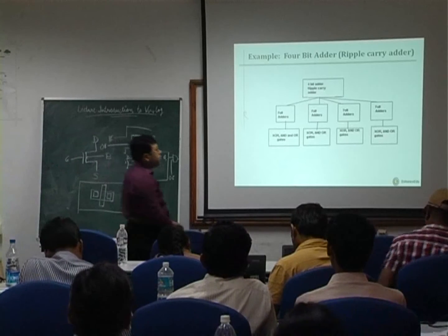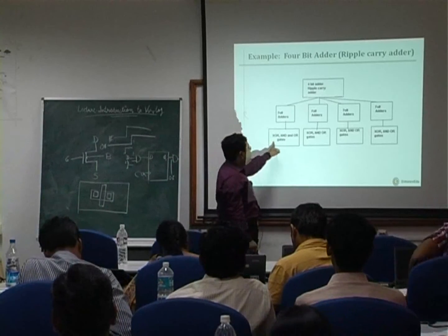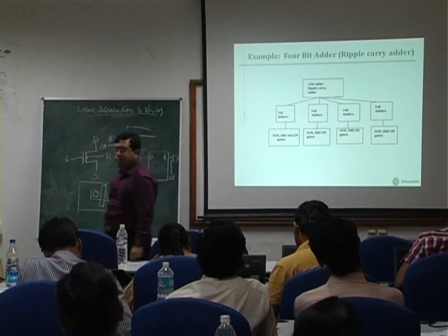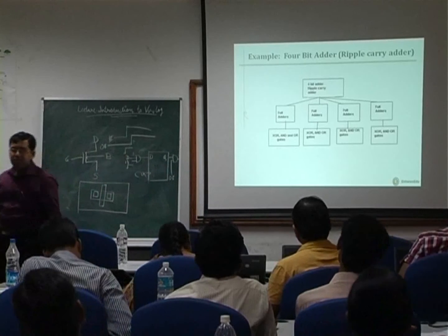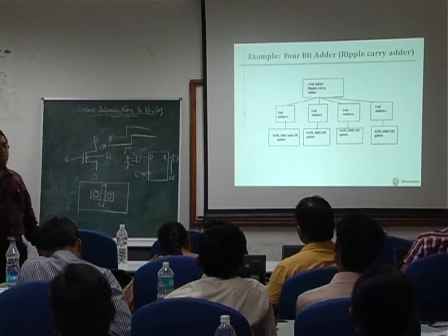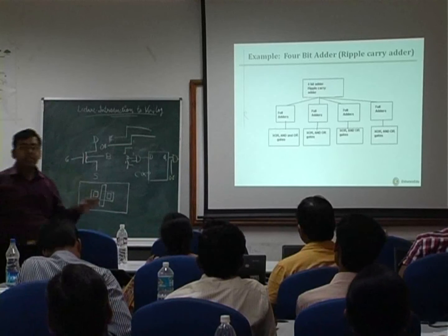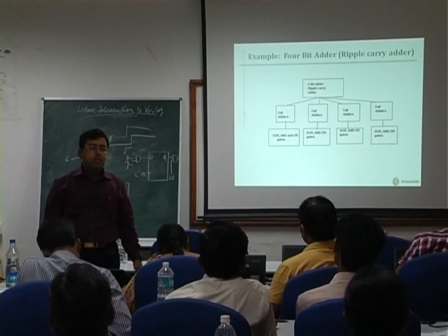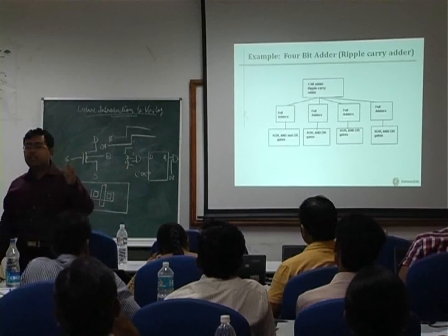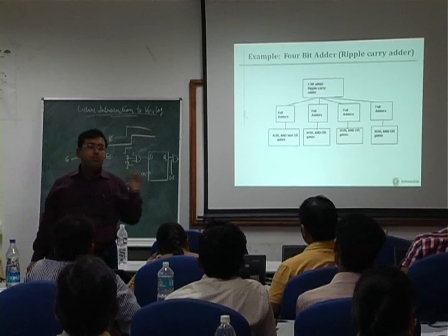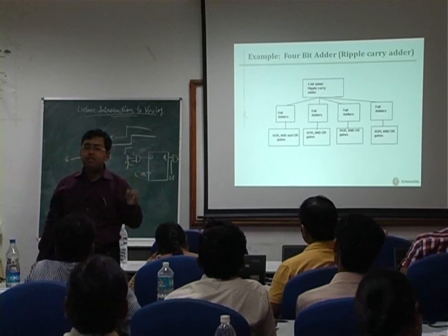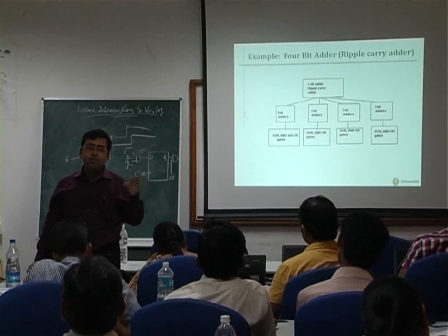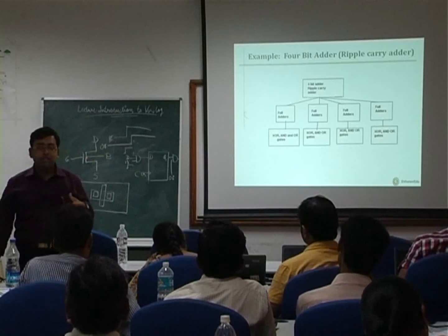that if you go by the top down approach, then the dimensions of all these XOR, AND and OR gates will be the same, because you are looking at each of these XOR, AND and OR gates identically. But if you think about it very deeply, then the loading effects of the different transistors used for implementing these XOR and OR gates are different.